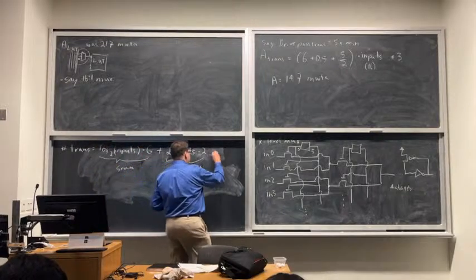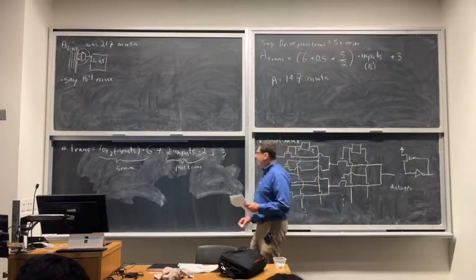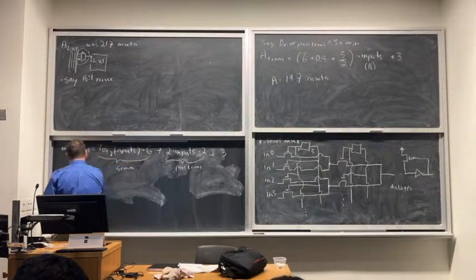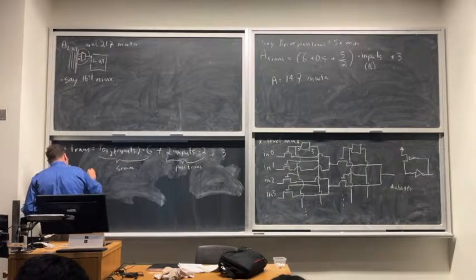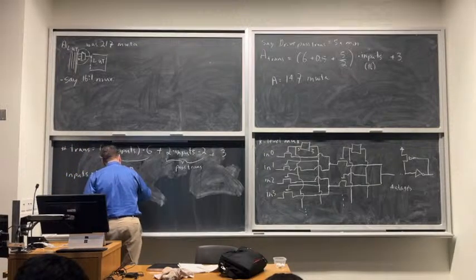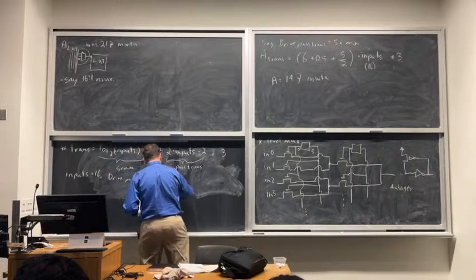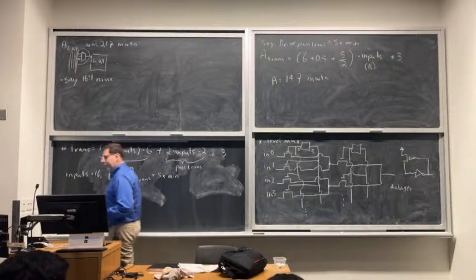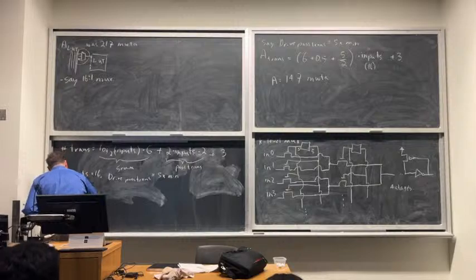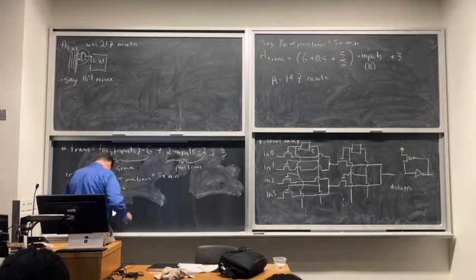And then I have this output structure, which is just 3 transistors at the end, same as always. Okay, so hopefully everybody's with me. If I do the same thing I did before, so if I say, okay, let's plug in inputs equals 16, and let's say the drive of the pass transistors, we increase it to 5 times the minimum, so we're going to upsize our pass gates. We plug in our simple area formula for a transistor as we upsize it, and if we do that, we get an area of 123 of these minimum width transistor areas.